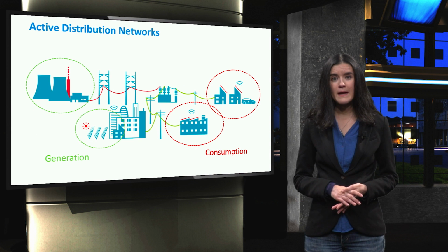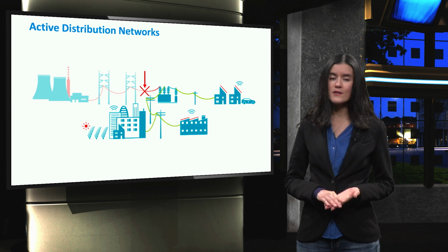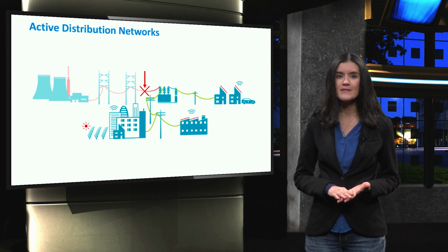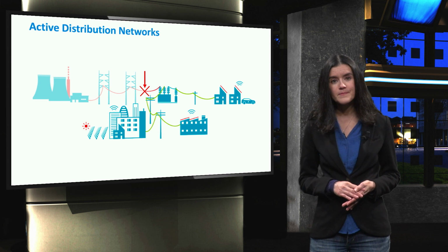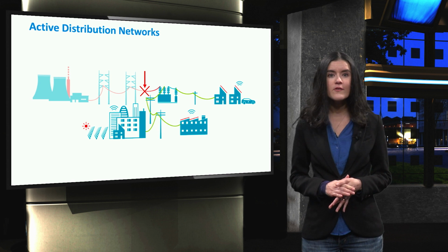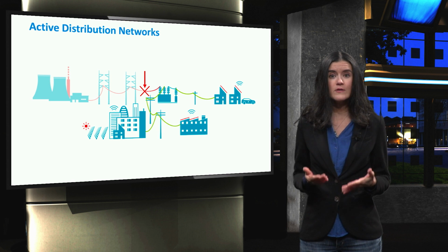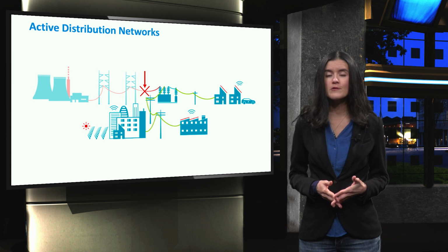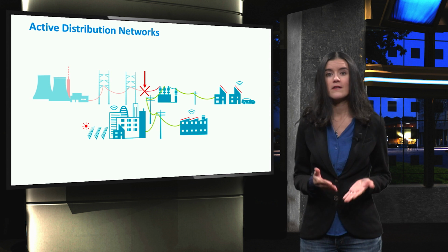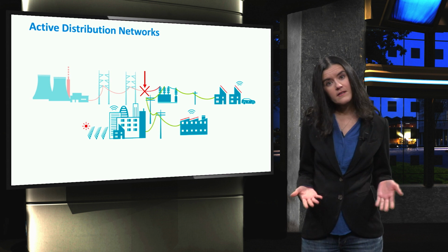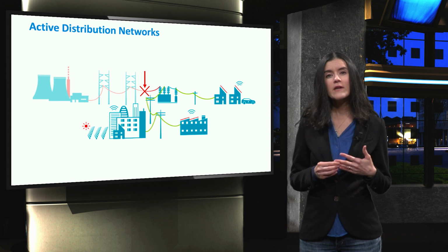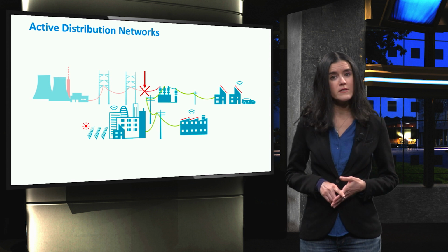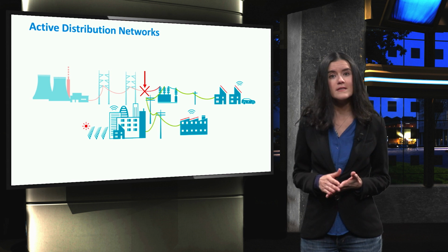Moreover, unlike passive ones, active networks have the potential to support standalone operations since generation is decentralized and it is often coupled with storage units. Additionally, the proximity of distributed generators to the demand sides makes it possible to obtain a reduction in transport-related losses. Finally, active networks have the potential to provide the network with support by relieving congestion and offering restoration after faults, among other ancillary services.